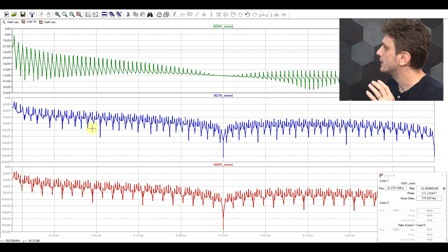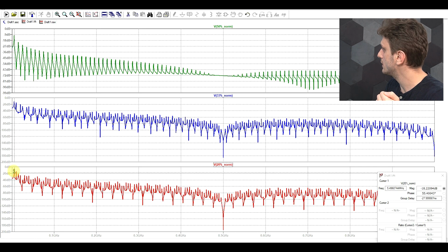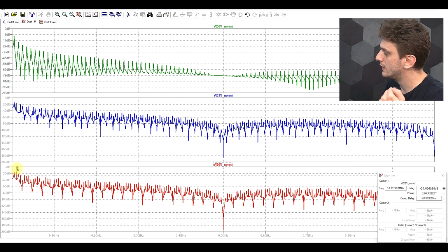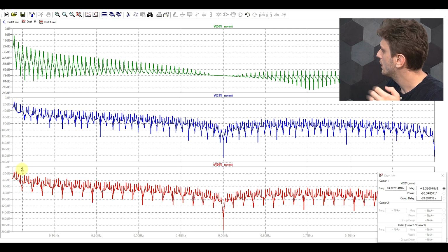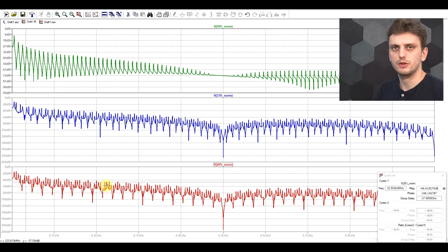But if we look at the other spectra, so the 33% or the 20% duty cycle, we have our fundamental at 5, we have a spike at 10 MHz, then at 15 and at 20. We don't really have one at 25 and so on. So the spectra will depend on the exact duty cycle. Normally in comb generators, what you use is 50% because it's easiest to obtain and it's easiest to control.